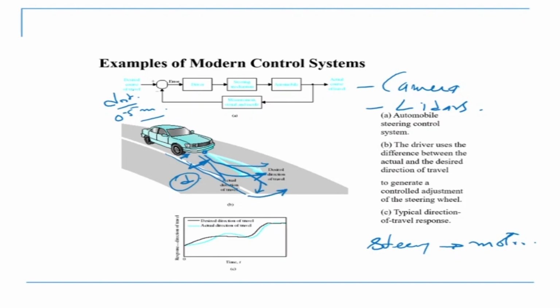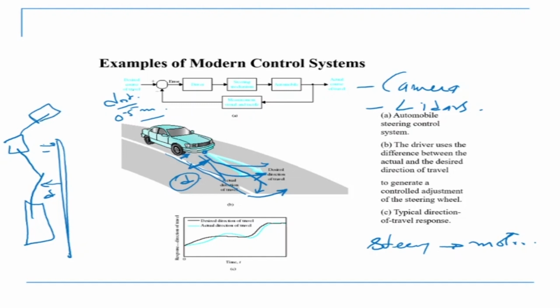Okay, so if I draw the top view, this is my line. The car is here, so it is traveling like this. If this distance d decreases, it will move the car that side. If the distance d increases, it will move the car this side. So by just changing the theta of the motor, you get the car following not exactly straight as shown here, but following the center line. This is how an autonomous vehicle works.